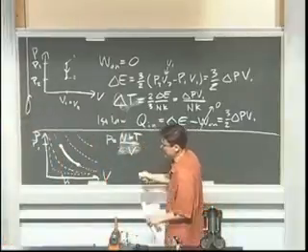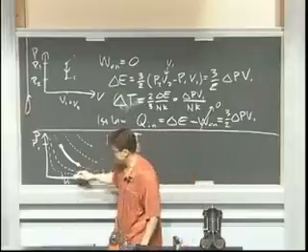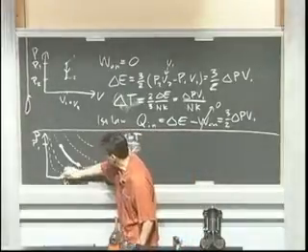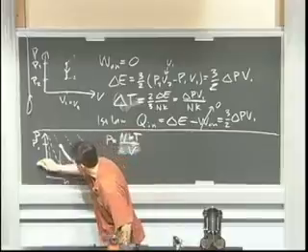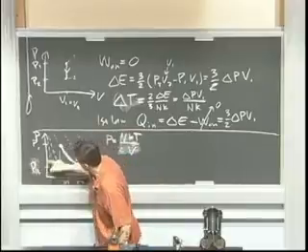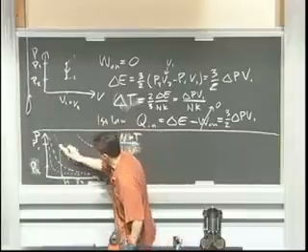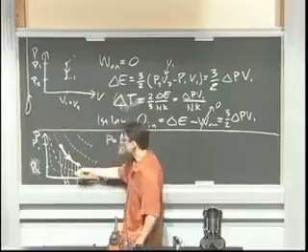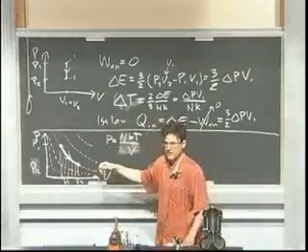If you have a curving trajectory like that, now when you calculate work, we have to worry about the fact that you have an integral. So here's our V2. Here's our final V. Does everyone see this okay? V1, V2, P1. Now we have 2 different P's and 2 different V's. We've got a P1, P2, V1, V2. Area under the curve is the work, just like always. We're going to the right. So is work on going to be positive or negative if I'm going from left to right in the diagram? Work on.